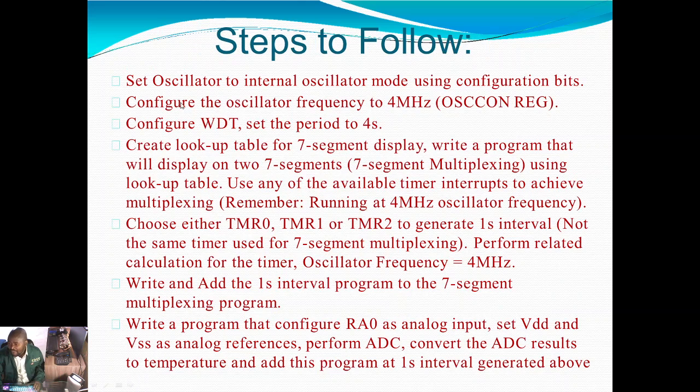We now managed to set our configuration bits to select the internal oscillator, set the internal oscillator to 4 megahertz, and unfortunately we couldn't achieve a time period of 4 seconds for this watchdog timer. The maximum available is 2.097 seconds. We set it to the maximum of 2.097 seconds. Right. Now we want to go and do this.